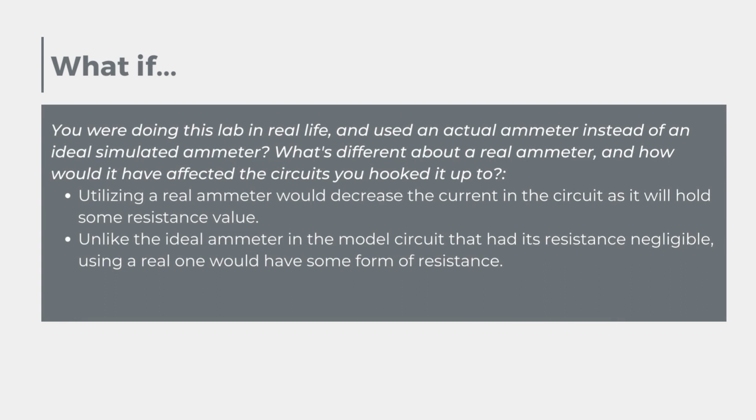So for our reflection questions, what if you're doing this lab in real life and use an actual ammeter instead of an ideal simulated ammeter? What's different about a real ammeter and how would it have affected the circuits you hooked it up to? Utilizing a real ammeter would decrease the current in the circuits as it will hold some resistance value.